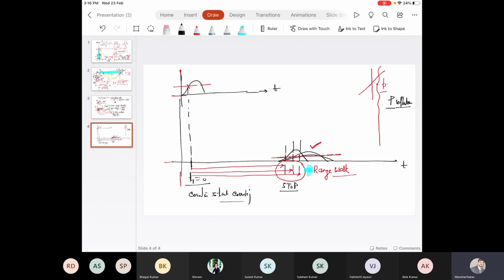So what is the reflectance, and whether it is sloping terrain or flat terrain? The way this energy pulse interacts with the object, the shape of the return changes. If it is a sloping terrain, the topology varies in that way, so in the return signal you can see the broadening in the shape.